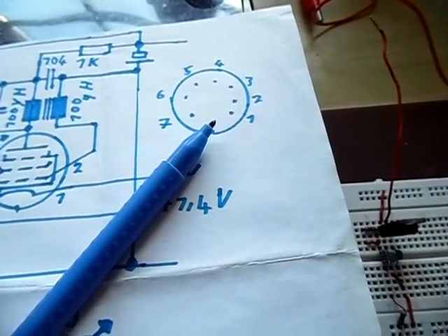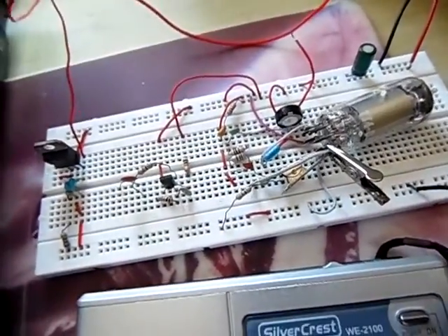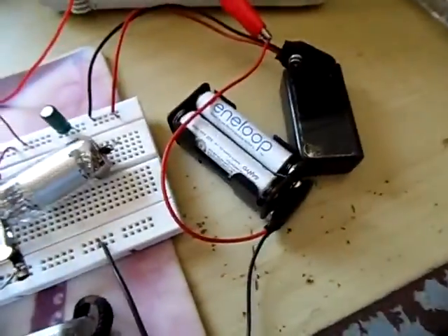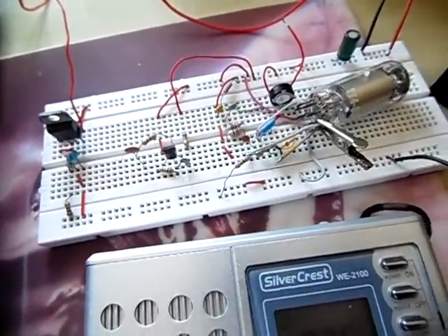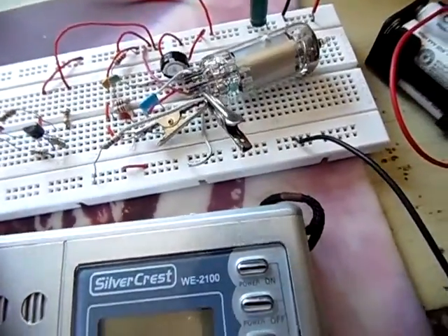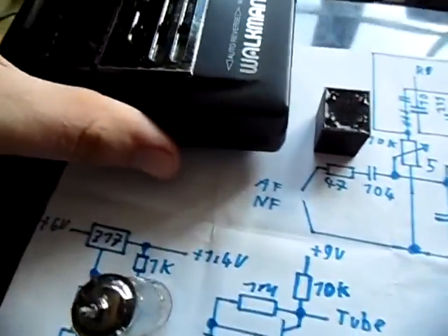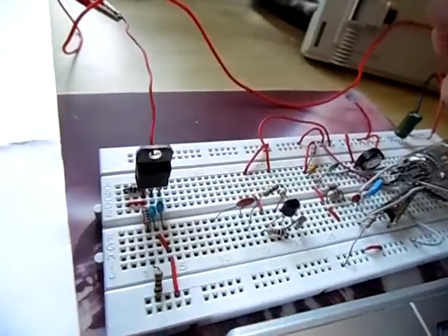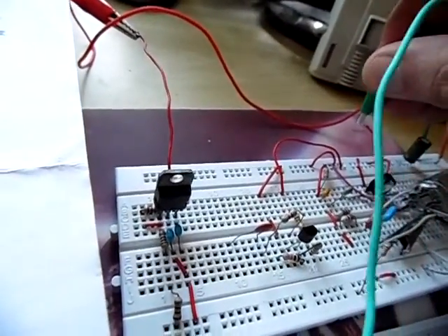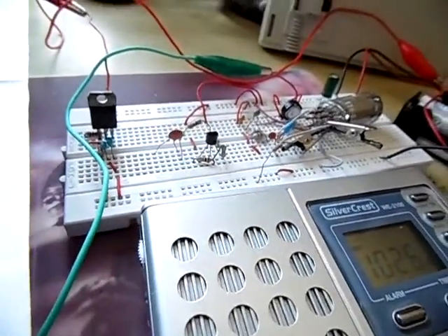Anyway, okay, so here's my circuit. I'll connect the heater voltage, which is, by the way, not 6 volts. It's 1.4 volts, but that's an electronic circuit that manages it. Anyway, so now the tube is on and we have a signal. Now I push play on my cassette player and I connect my cassette player to the audio input from this tube transmitter, which is of course quite dodgy with one hand. But hey, I'm making this a live video.